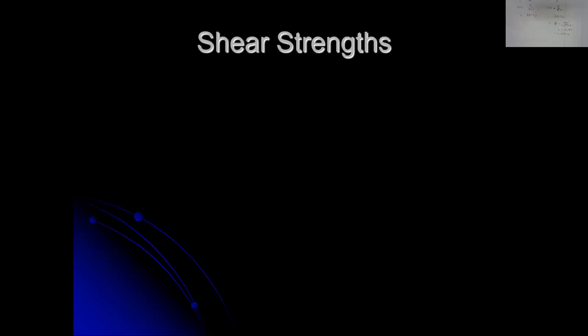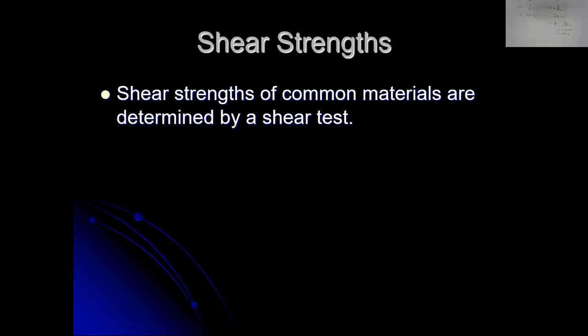without shearing? Now, shearing, like we saw last week, doesn't really have a strain to it. So we don't have an equivalent to yield. We only have ultimate strength. So we only typically care about ultimate strength when talking about shear. So the shear strength is typically an ultimate strength.